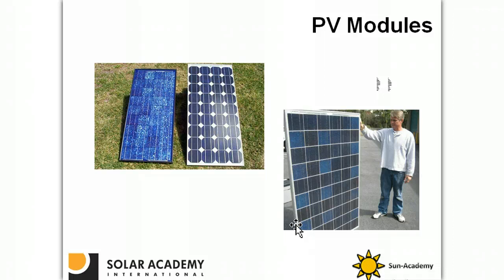First generation PV modules typically used 36 series connected solar cells, which produced a high enough voltage at high operating temperatures to charge nominal 12-volt batteries. Now, newer, larger modules have 60 or 72 or more series connected cells designed for high voltage applications with interactive inverters. Most listed modules today can be connected in series up to a maximum of 600 volts DC, and some allow configuration up to 1000 volts DC where permitted.